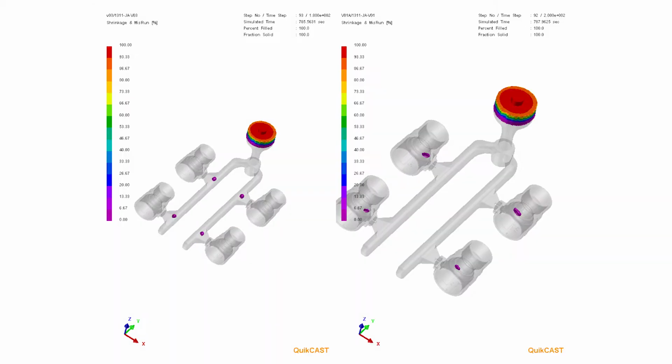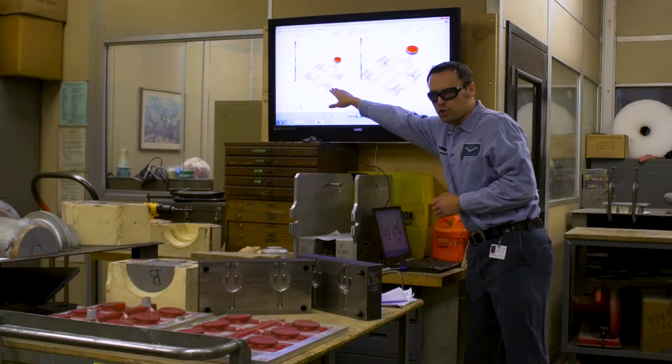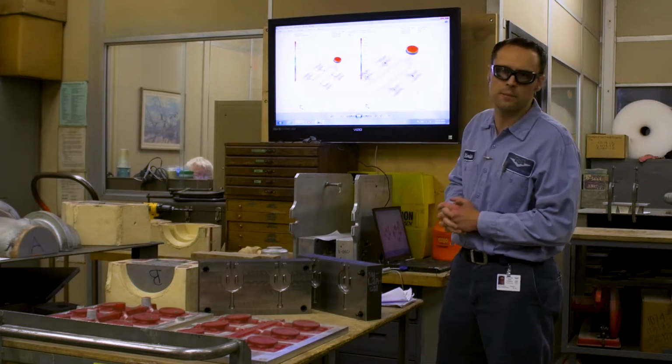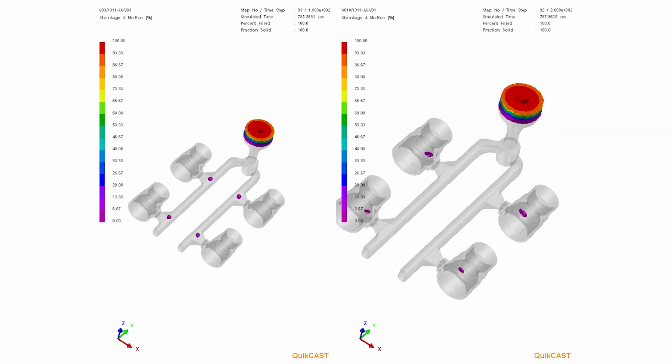What we do is look at common defects in casting, for example shrinkage porosity. Obviously, we had a gating design on the right-hand side where you had shrinkage in your casting, so you don't want that. So we changed the gating, and we're able to pull the shrinkage inside the gating, which is what we want, so that the gating gets recycled. That's not something we send on to the machine shop. So that enables us to run design iterations before even having to cut the tooling.